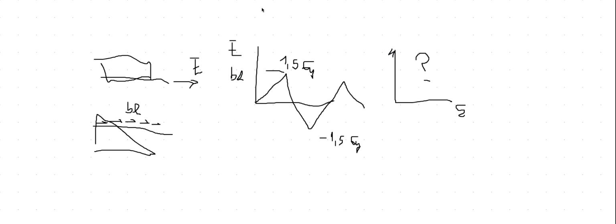So plasticity will not happen throughout the bar, but only the part where you're reaching beyond. And so the trick is how big is the mesh that you have to use. You can use 1, 2, 3, 4 elements, whatever you want. So try to play a little bit to see how it goes, and hopefully this will kind of demystify.